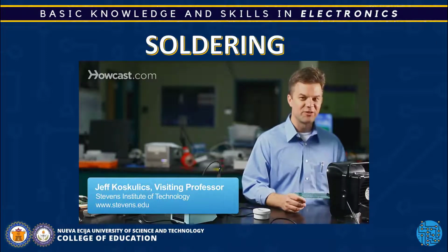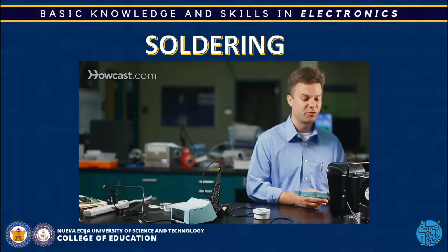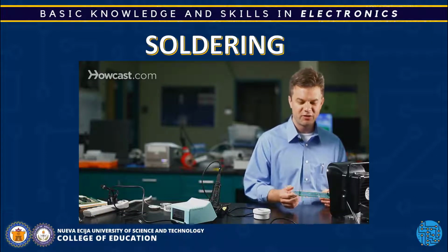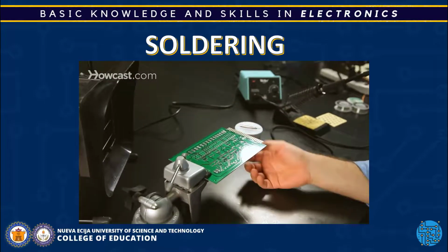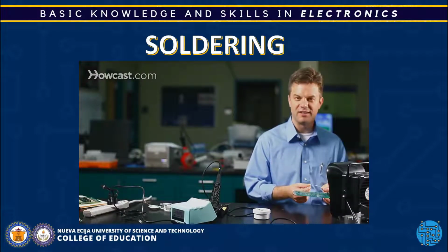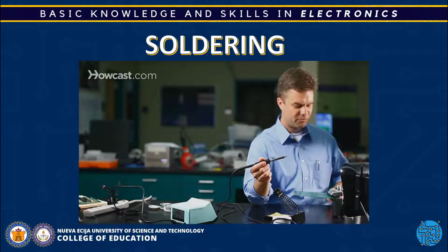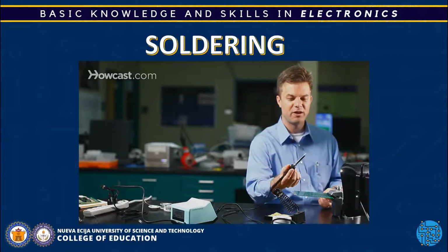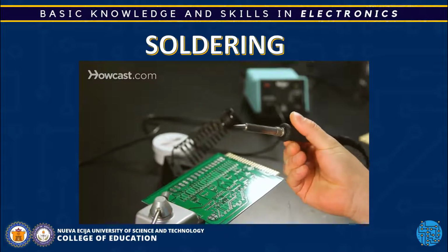Alright, what is soldering? It's a really good question. Soldering is a process of joining different types of metals. And in the case of electronics, we're really interested in joining copper to, say, a printed circuit board. So we have solder, which is an alloy, usually tin and lead. In order to solder, you need to melt the metal by adding heat. And so we use an iron, which has a pointed tip like this.